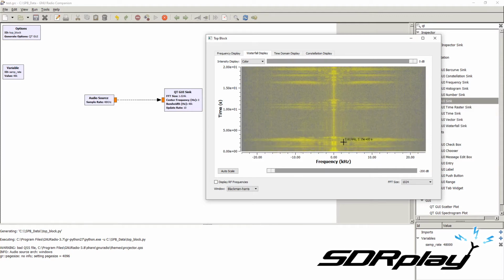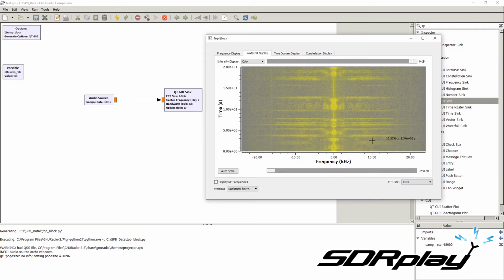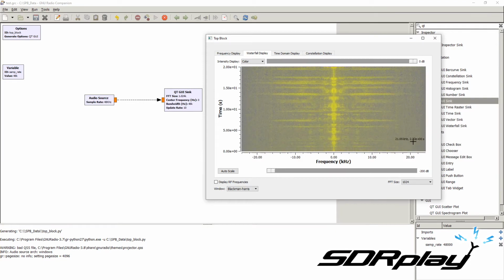Let's say the whistle is something we want to know a little bit more about, so we want to be able to isolate the whistle between all the different frequencies, because now you see we have 24 kHz of range in audio, which is half of the sampling rate. But our whistle is around 1 kHz, so we have 23 kHz of unused bandwidth that we do not need.